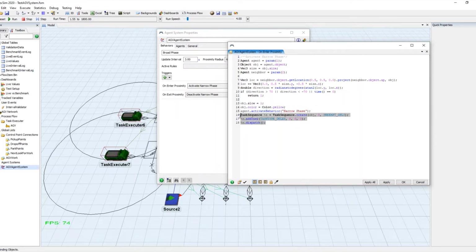And then I just give him a task sequence that preempts him and does nothing. What that will do is break him off of his current travel task and have him do nothing, and then he'll just start up the task that he was just doing. So he will restart his task, reevaluate that initialize travel, and figure out which phase he's in by the load type I have set. By the fact that I've set his slow label, he'll go into the slow load type.